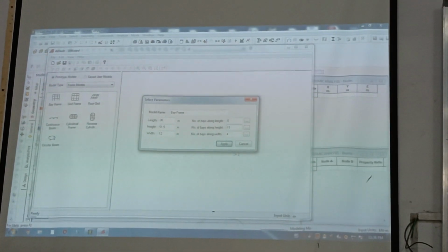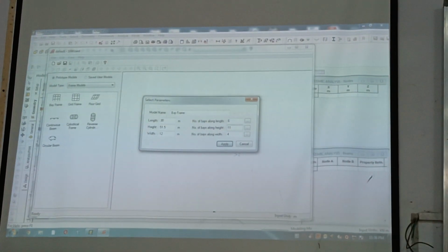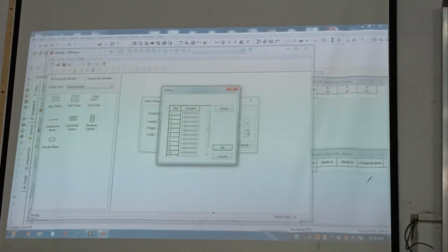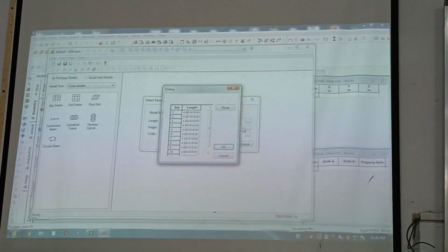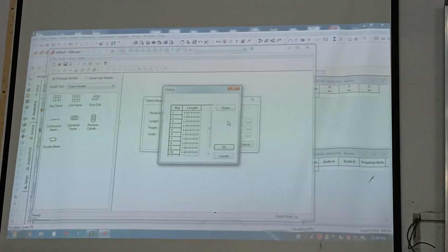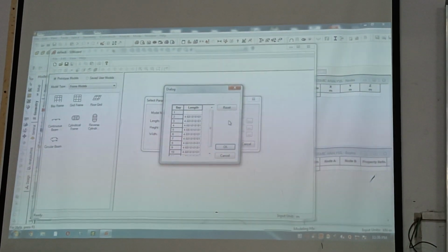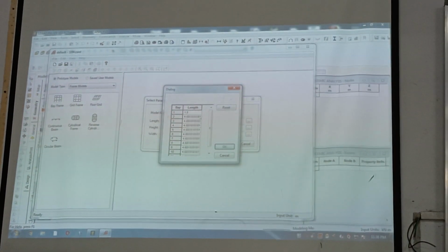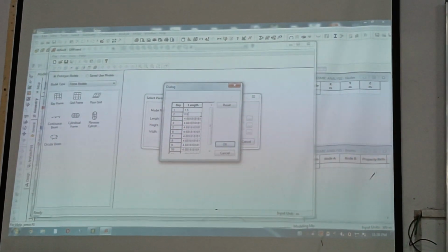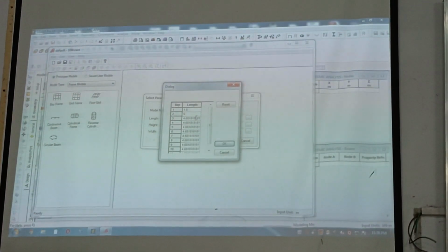That 51.5 is now divided by 11. Equally it will take, but now in our case it is not like this because typical story height we have taken 5 meters, right? So now we have to change it. Assume that base height is of 1.5, nothing but height of plinth. Next, all remaining typical story height is of 5 meters each.